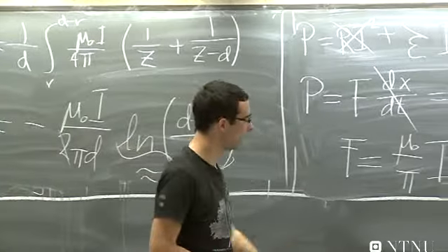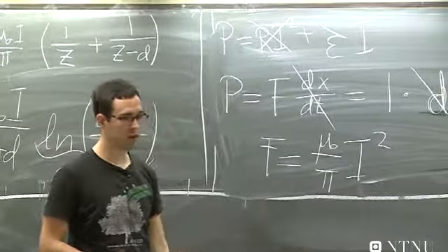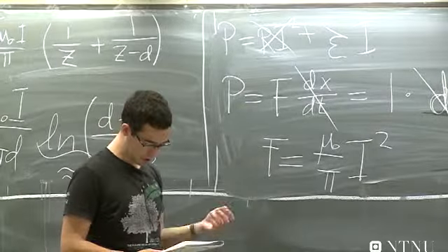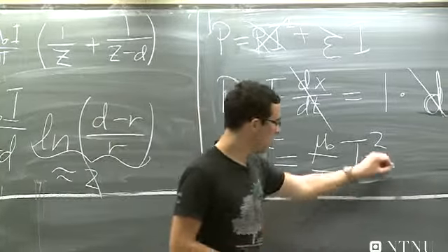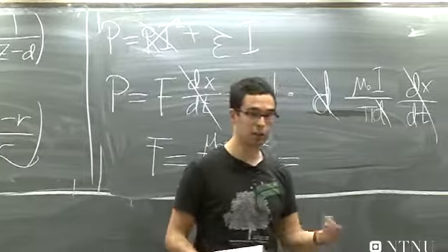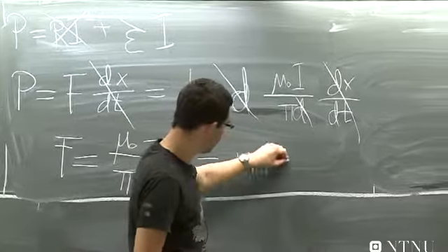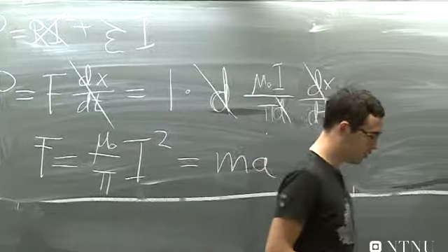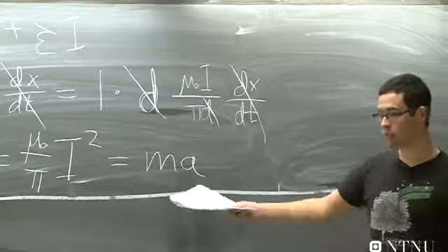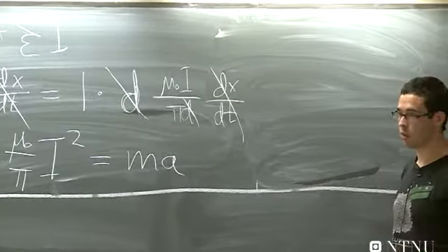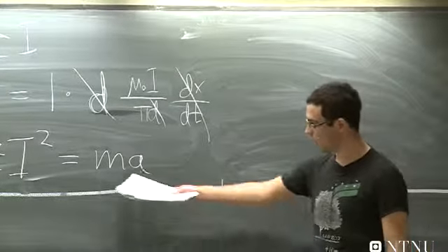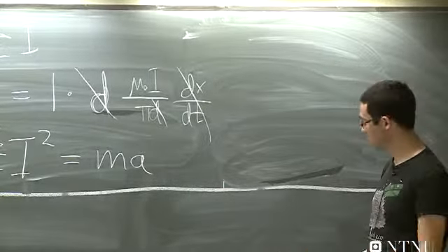That's a nice property. So you get a big fat current flowing and you got a lot of force. And this, if you then again neglect friction, which is ridiculous, but we'll do that because it's on the blackboard and we don't have too much time, I'll just set equal to the acceleration of the projectile. M is, of course, just the mass of the projectile.